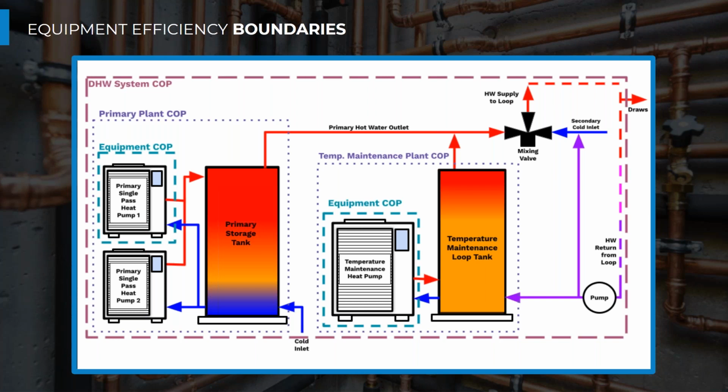So the amount of insulation on your piping, the size of that piping and its relationship to Appendix M, the location of that piping, whether it be in a conditioned space that's always 70 or an unconditioned space that's tracking closer to 50 degrees, all have a significant impact on the heat loss rates. And that's why we typically see them vary so much.